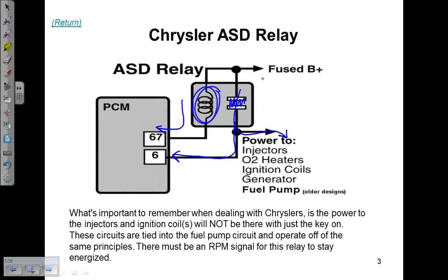of the computer board. Now, the reason I have this one in there is, in particular, when it comes to no start diagnosis and when you have no spark. And what Chrysler did is the ignition coils are on this circuit. And so it's kind of different than some of the cars, because part of a no start diagnosis on an ignition coil would be turn the key on and check for power on the ignition coil. There should be power there.